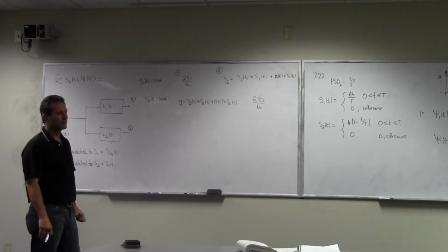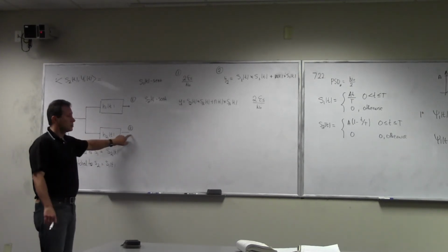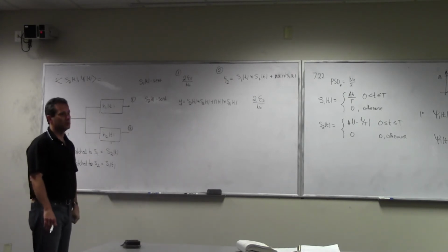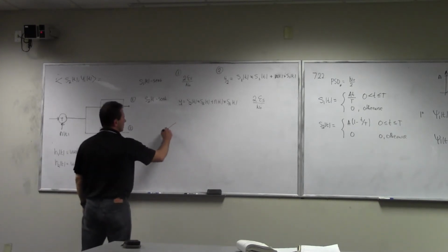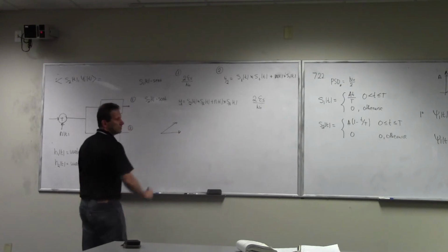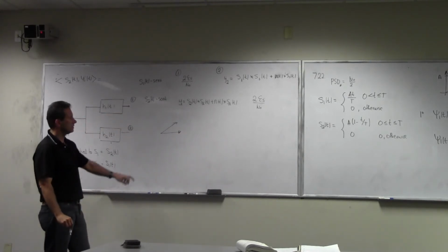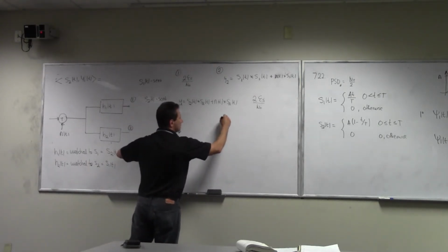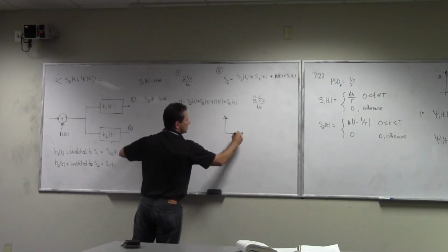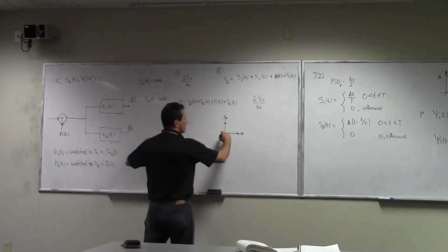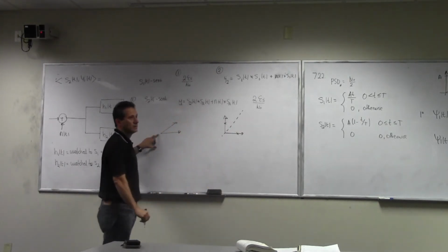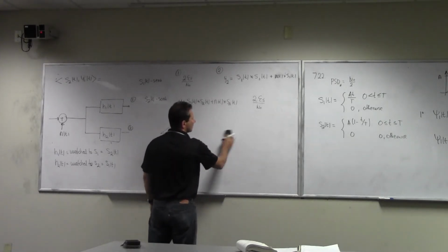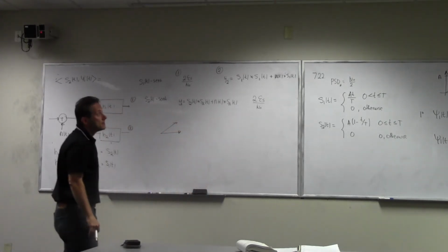Yeah, you're saying some of the energy from the other signal would show up here. And then the question is whether the presence of this energy can put me over the decision boundary. But Dr. K, even when we use our correlating, we have orthogonal filters. Yeah, when you do correlating, you have this, and you're signaling with these points. But one of them is going to be showing up in both of them anyway, because they're not orthogonal.